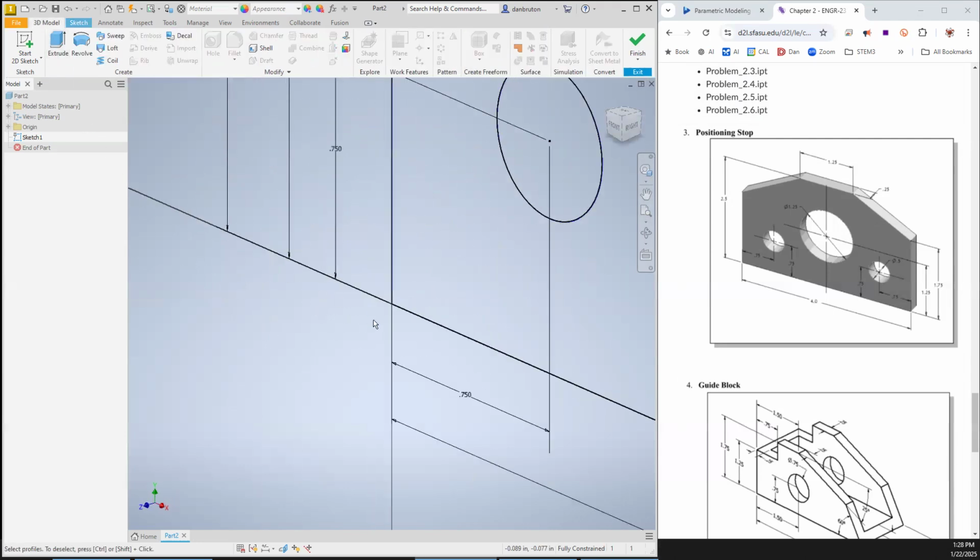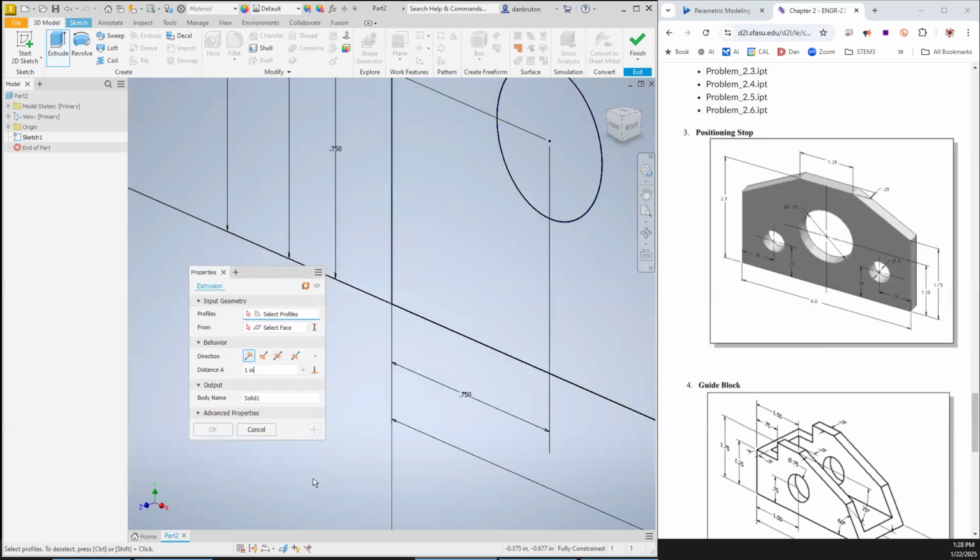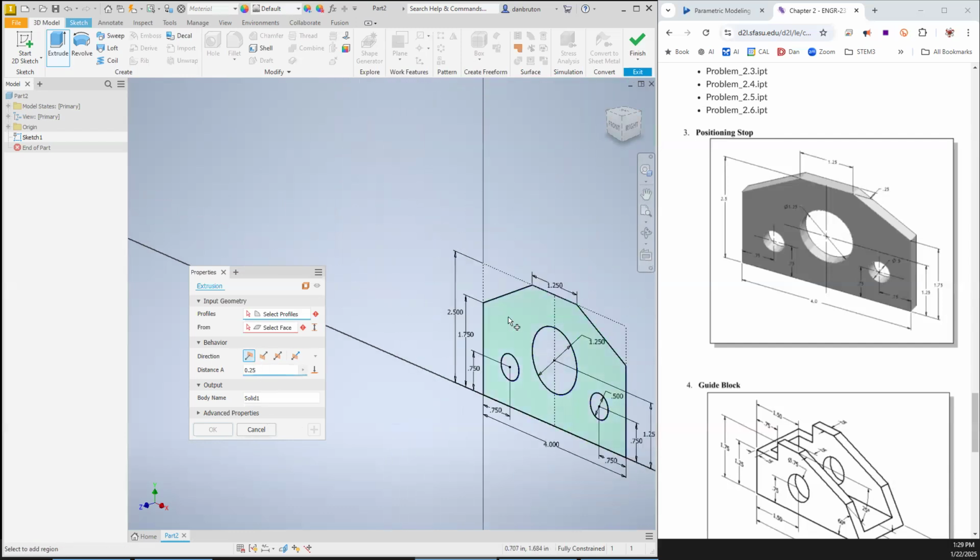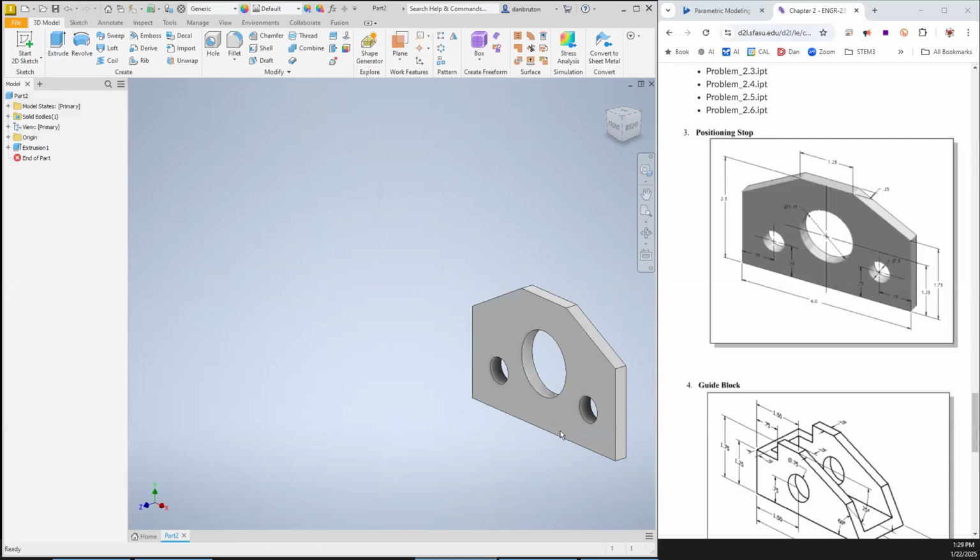And of course, what we want to do, extrude came up on the other window, is we want to extrude this out a quarter of an inch out. Okay, now it looks like I started clicking before I noticed where I was typing. So there's 0.25. Let's just hit that right there to see if it'll show us a preview. If we click on it, hopefully it'll come out just a little bit like that. And then like so.